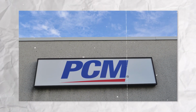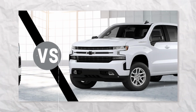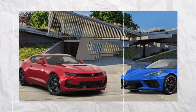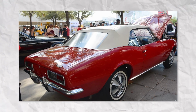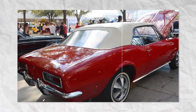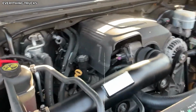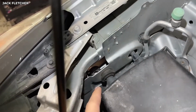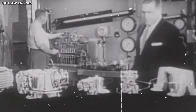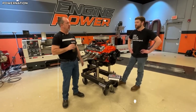Navigate to the PCM section, which stands for Powertrain Control Module. This is your main engine computer. Look for the configuration settings or as-built data section. Here you'll find hundreds of hexadecimal codes that control various vehicle functions. The specific codes for throttle response vary by model year and engine, so you'll need to research the exact codes for your vehicle on ForScan forums. But generally, you're looking for parameters related to throttle progression, pedal position scaling, and boost control on turbocharged engines.